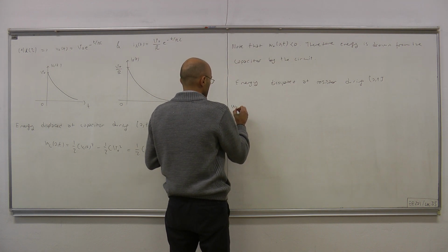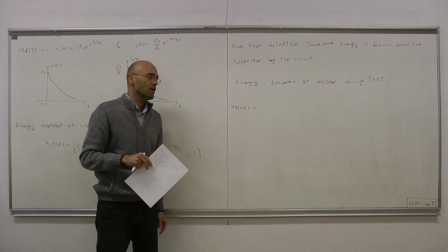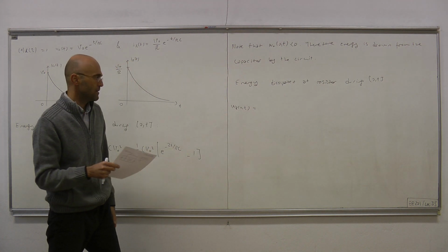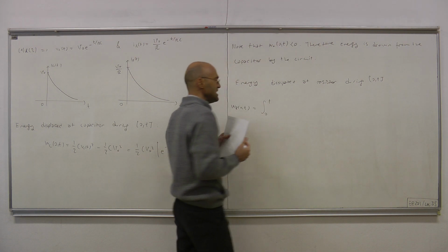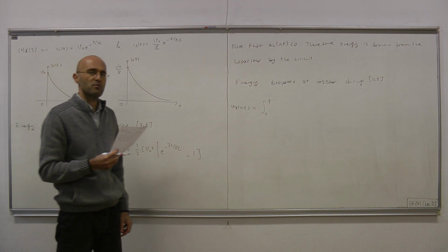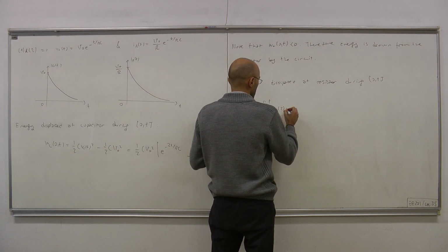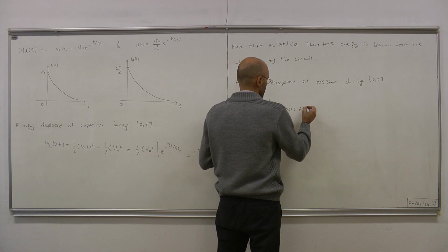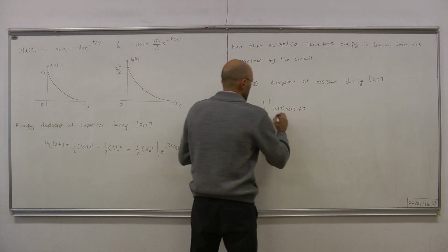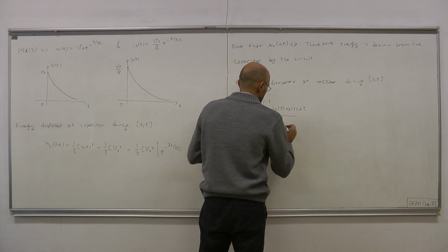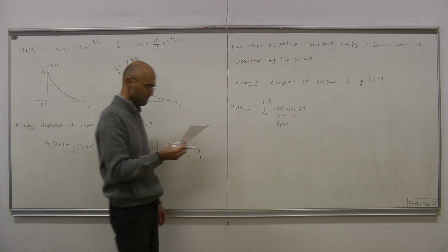Okay, WR(0,t), the energy dissipated over resistor for the interval 0 to t. And that equals the integral of power, because power is the rate of change of energy. IR(tau) VR(tau) d tau. Okay. This is PR(tau), let's say, the power of the resistor.